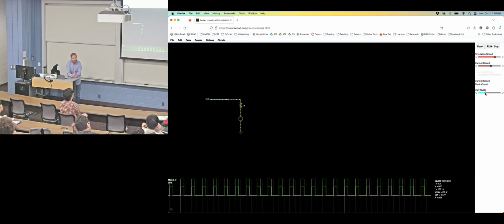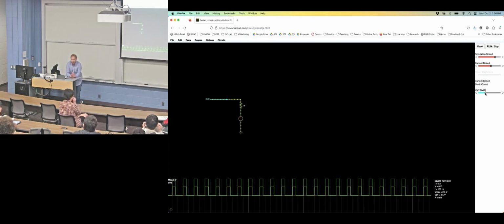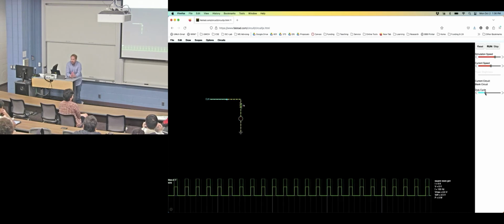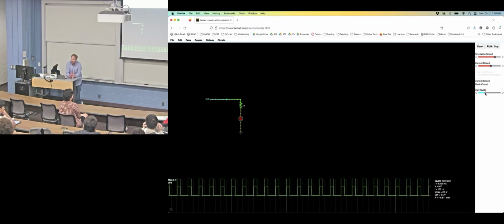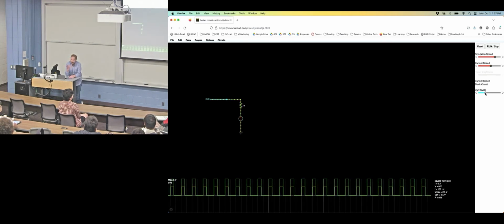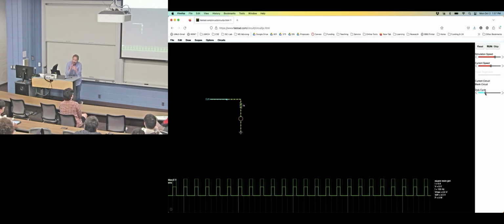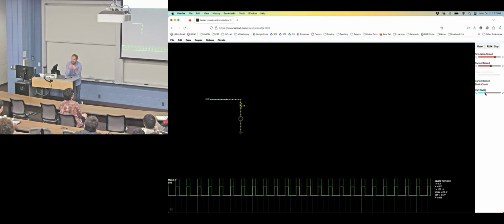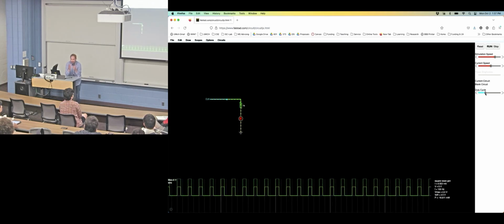A lot of things you can control. One of the things to think about with embedded systems is that microcontrollers and digital systems are really bad at analog, like real bad. You need an external converter, or we'll talk about analog to digital and digital to analog converters later in the course. But generally it's bad. So we almost always try to encode information in something that computers are good at measuring. Computers are good at measuring the passage of time.